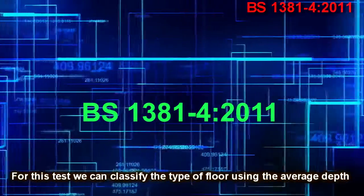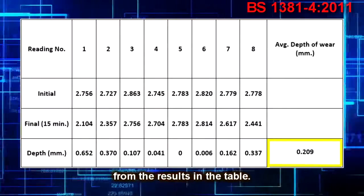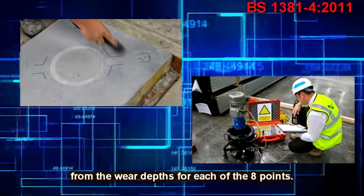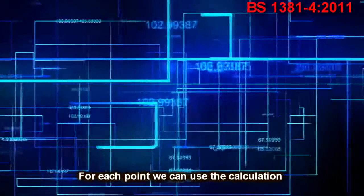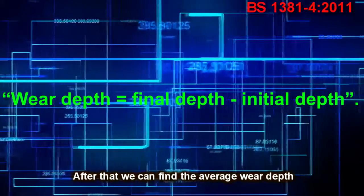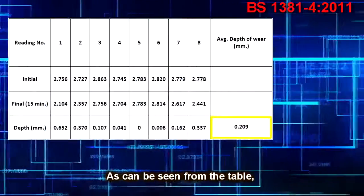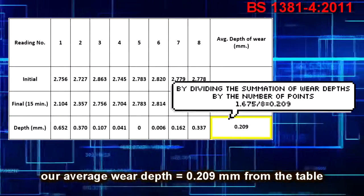For this test we can classify the type of floor using the average depth from the results in the table. As for the table, we can find the average wear depth from the wear depths for each of the 8 points. For each point we can use the calculation: wear depth equals final depth minus initial depth. After that we can find the average wear depth by dividing the summation of wear depth by the number of points. As can be seen from the table, our average wear depth equals 0.209 mm.